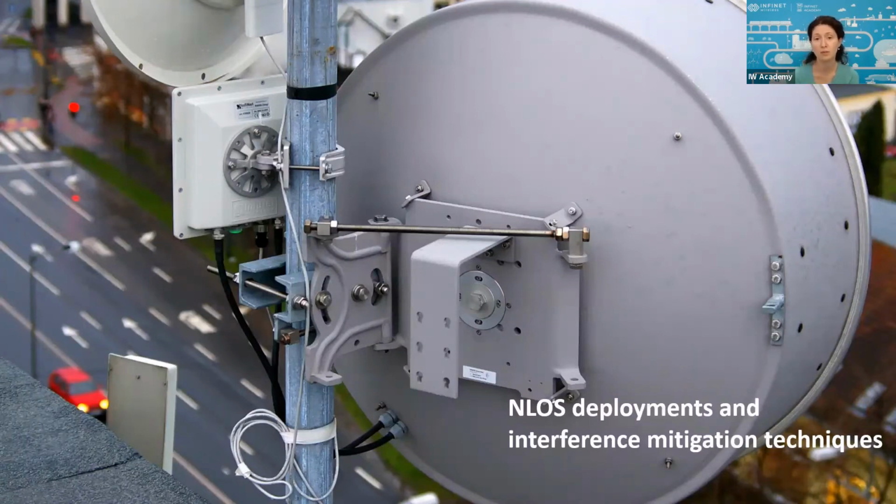It's hardware dependent for the R5000, but for Quanta and XG, it is available for all the units. And it will scan the spectrum automatically and switch to the least interfered frequency. Okay, so remember instant DFS.